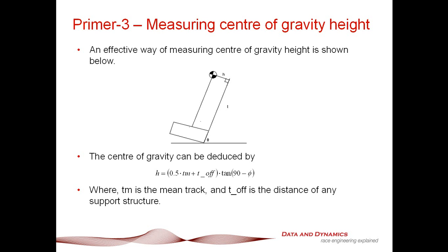The reason you want to do that is to keep the platform stable so you can get a good measure. And once you've got the CG height, you can then let the tire pressures down to hot tire pressure, and then you simply offset your CG height from there.